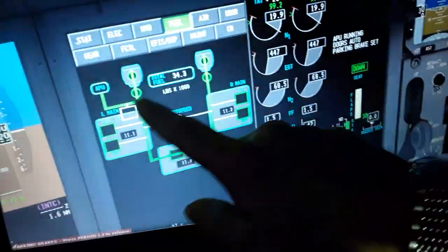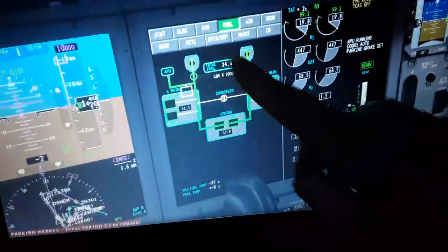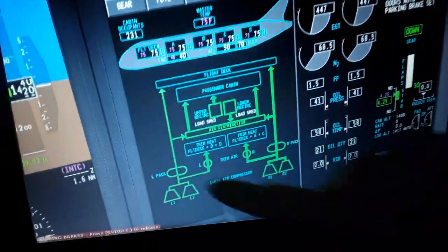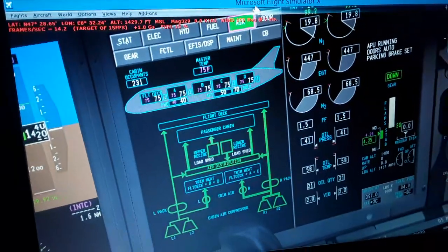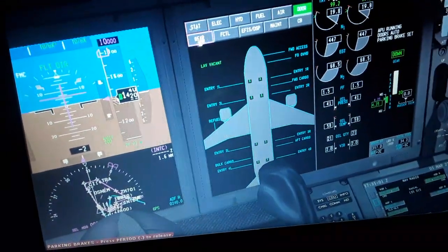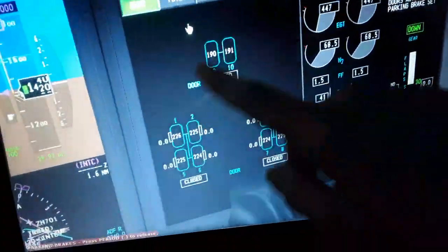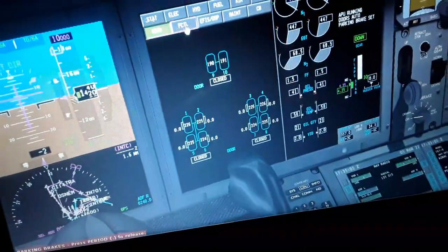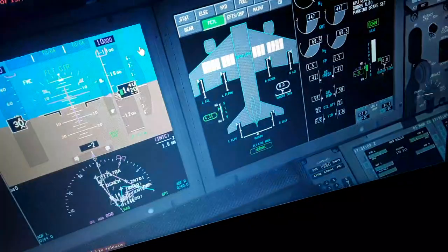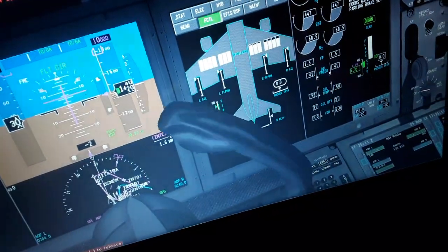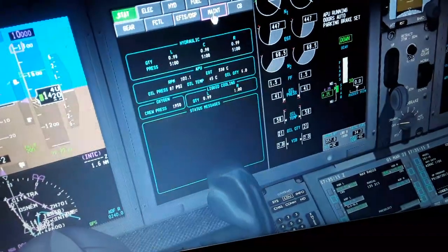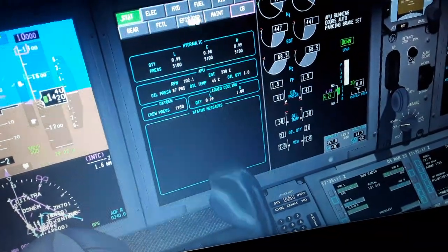This is automatic. Also the lubricant and the oil. We don't need to do anything from the FADEC. Also air pressurization from the engines, cabin pressurization, oxygen. Doors are closed, the cabin can be pressurized, the gear, temperature of the brakes, and pressure of the tires. Also flight controls over here. You can see the deflections left and right, wing climb, descent, rudder pedals like this. So we have the FX display like this, status, maintenance over here, circuit breakers.